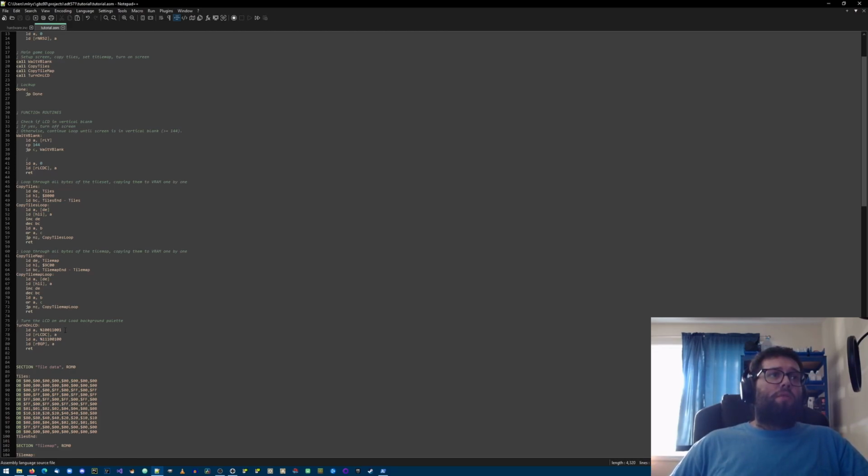So this 8-bit piece of data here, this byte of data, is going to tell the screen to turn on and make sure that it's viewing the tile set at address 8000 and tile map at address 9C00. Once we've done that, we send that to the LCD control register.